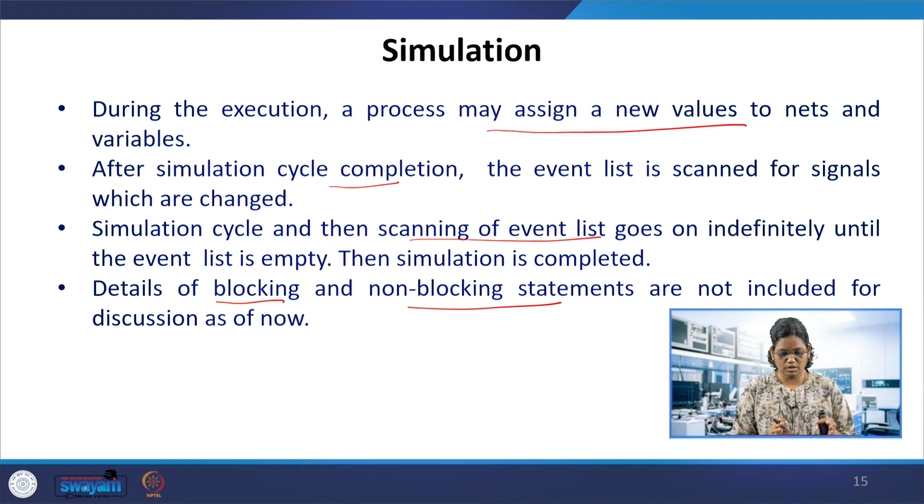Right now, in the modules we have seen, the concurrent statements are considered to be one software process. The complication can arise due to instantiation, or looping behaviors inside a procedural statement or always block, which can cause the simulation to stop, be suspended, or wait. If a delay statement is encountered, it gets suspended and goes to the next one in the event list.